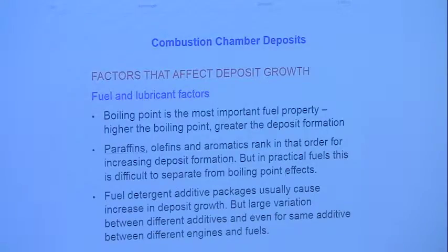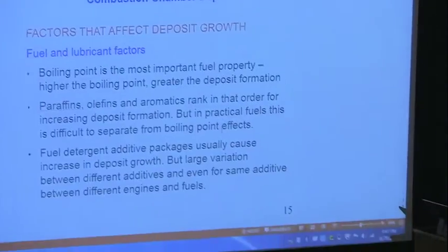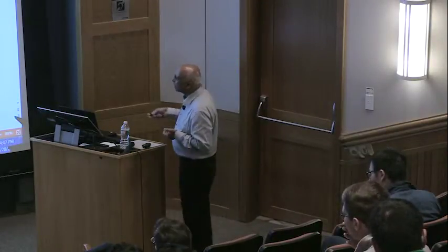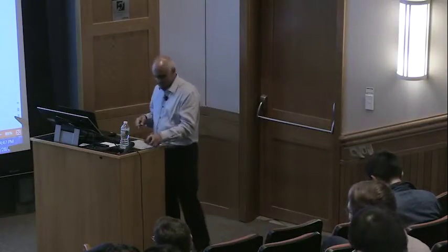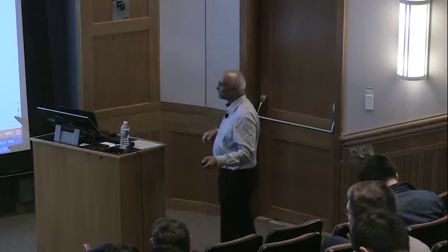And fuel detergent packages, which, as I said, are needed to control injector and inlet valve deposits, usually increase deposit growth because these detergent packages are heavier than the gasoline, generally speaking. They are high boiling point materials. But there is a large variation between different additive chemistries, and some companies make a big deal out of the fact that their additives don't produce that many deposits. Some of it is justified, some of the claims are not.